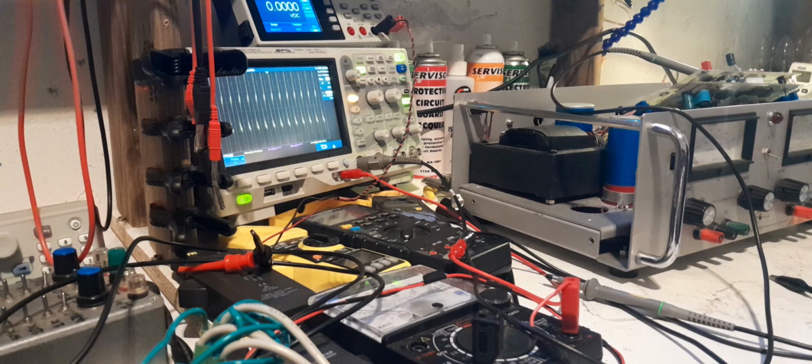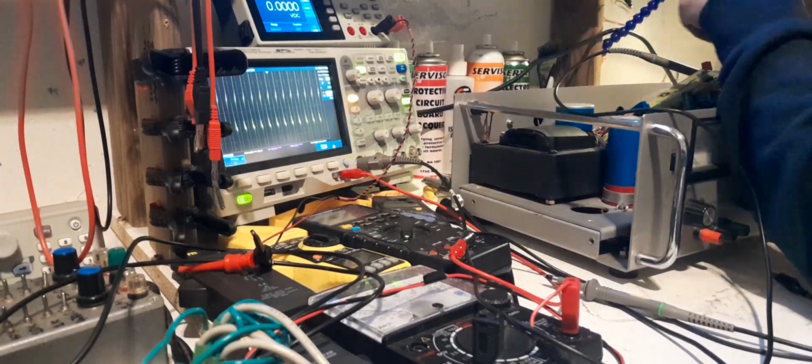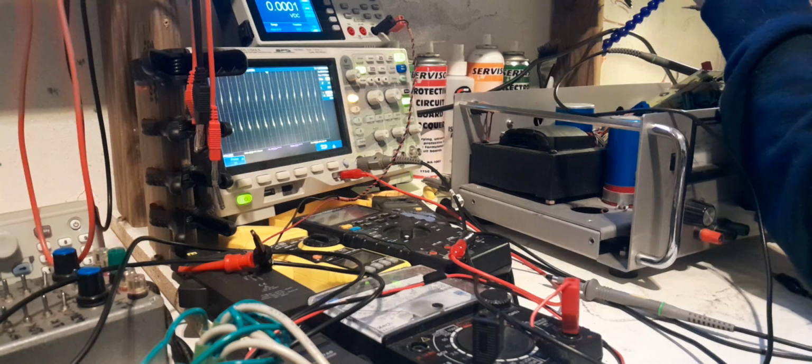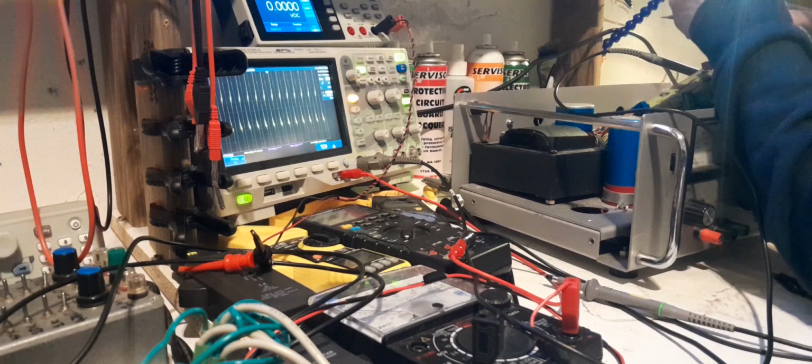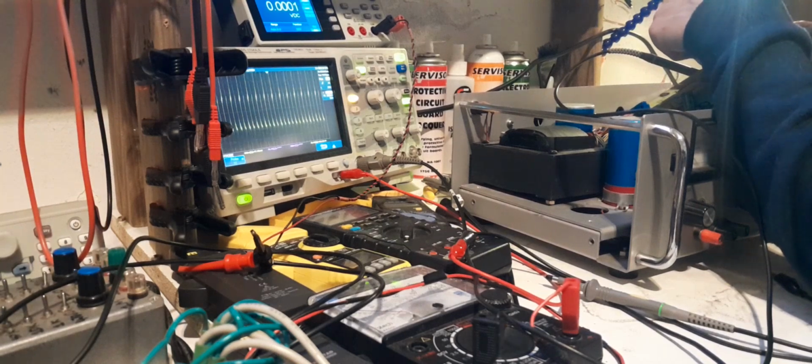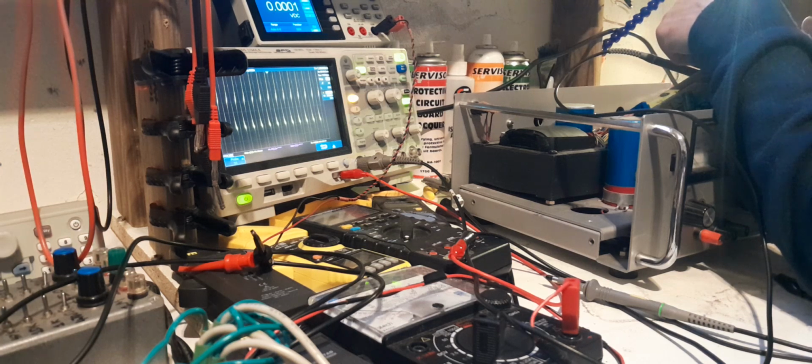I've already tried sticking caps across the reference on the top board to no avail. And the only other op amp on there is the one that drives the panel meters, and that just appears like it's out of range. I've got to redesign the input bias circuitry. So I was already thinking about just putting 2 different op amps in there just for the panel meters, because I'm not so fussed on the accuracy of them so much. Like I am, but not to the degree that I am with the regulation itself, of course.